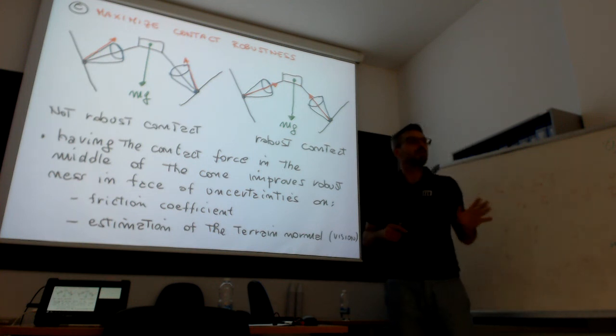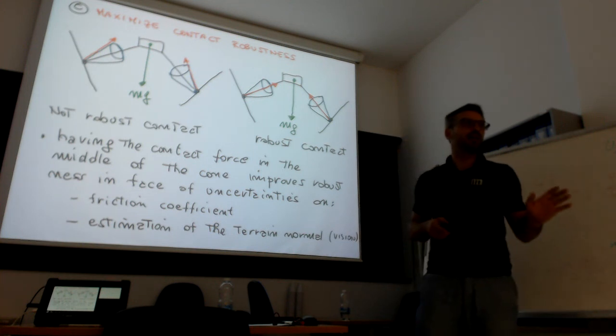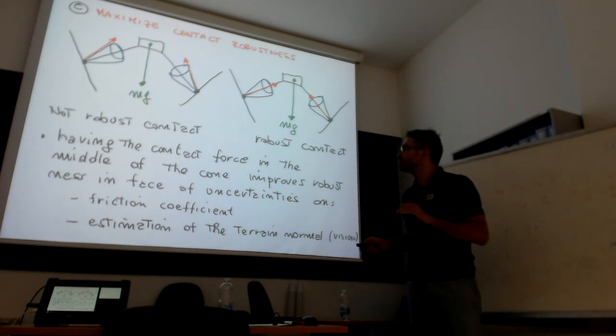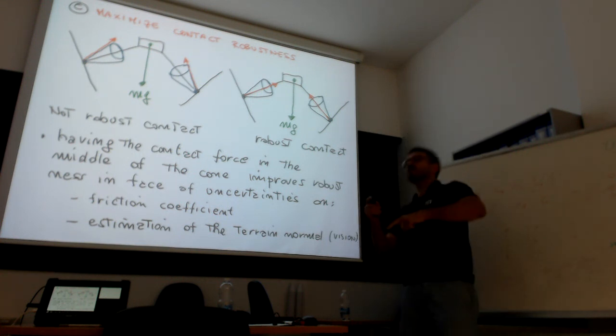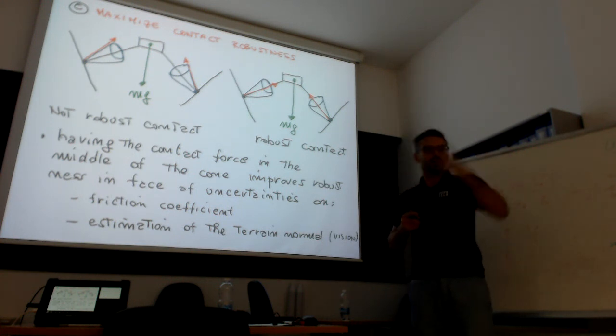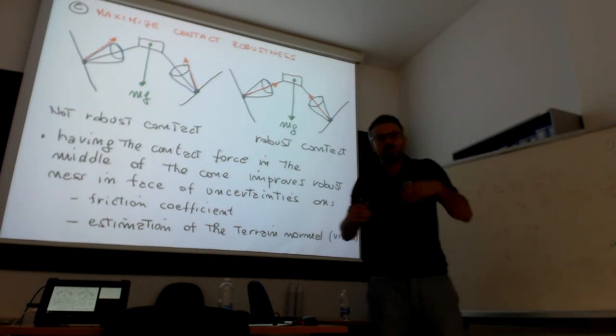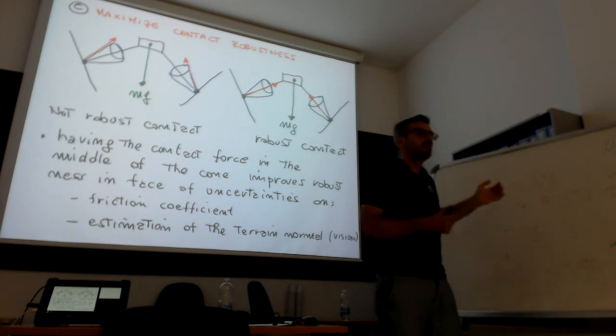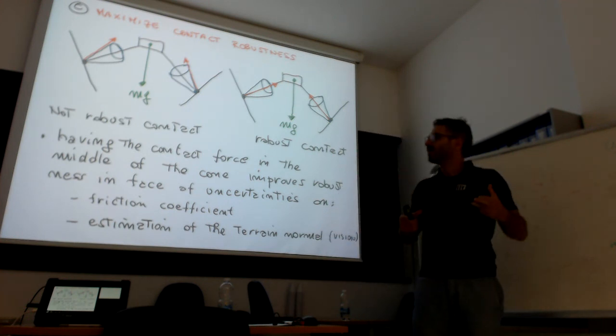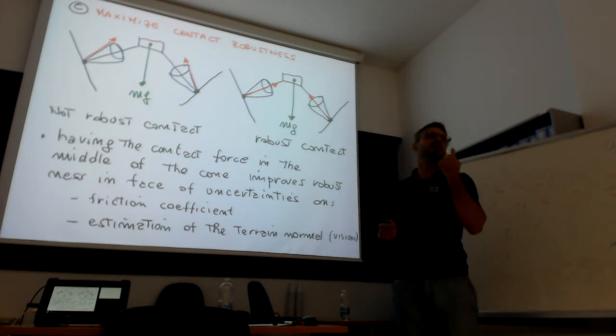But look at the quality of this normal, and I am afraid to use them in a controller because sometimes they are just like this, you know, it creates a cone like this. So what I do normally, I use my nice terrain plane estimation. I fit a plane through the stance feet, and I say that is the normal.